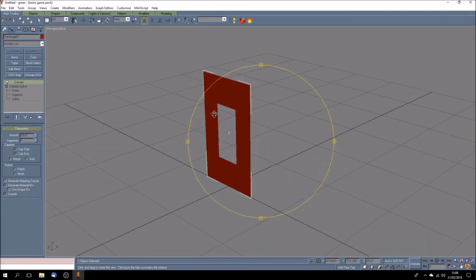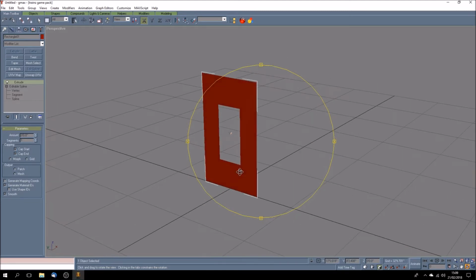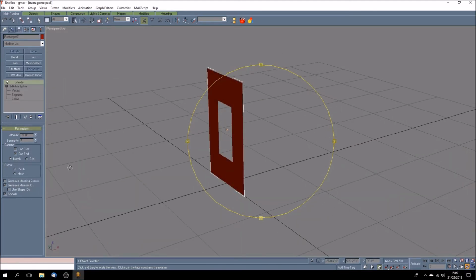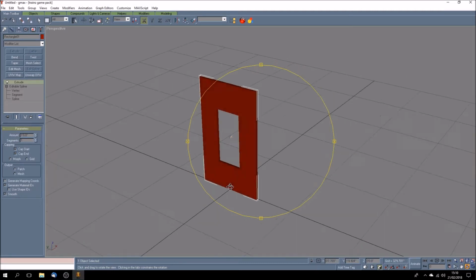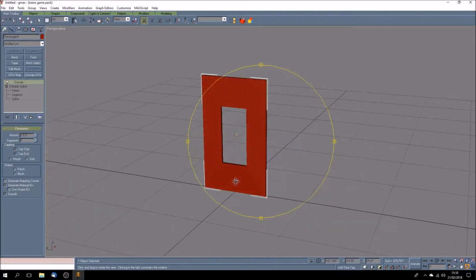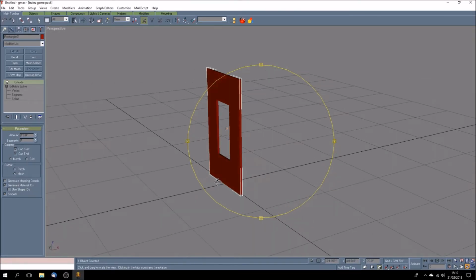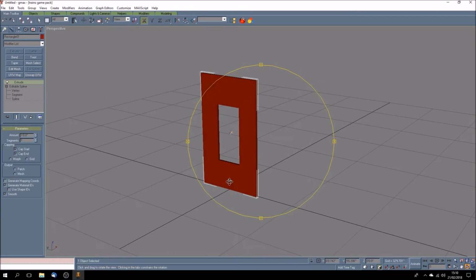If we want a wall and we're going to put a window in there, now nice big industrial wall, probably have a window about a foot set back, so we want a depth in there between these two faces of about a foot. And that's exactly what we do. We come over to where the parameters are set for the extrude function, and it's 0 at the moment, so we're just going to change that to 1 foot and then press enter, and there we are. We've now got a wall which is a foot thick.